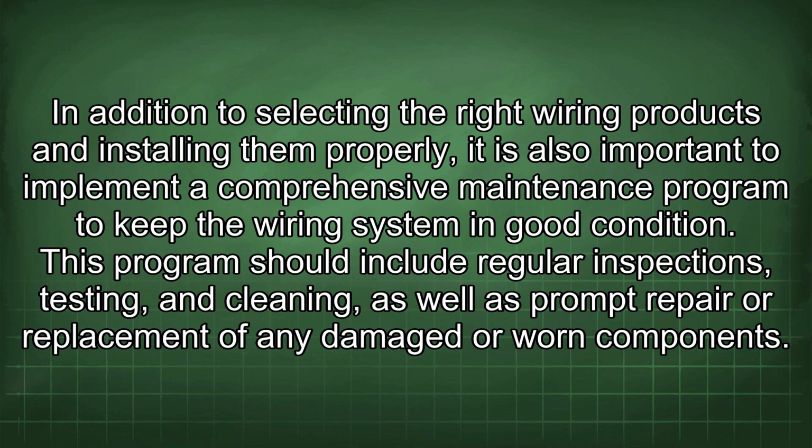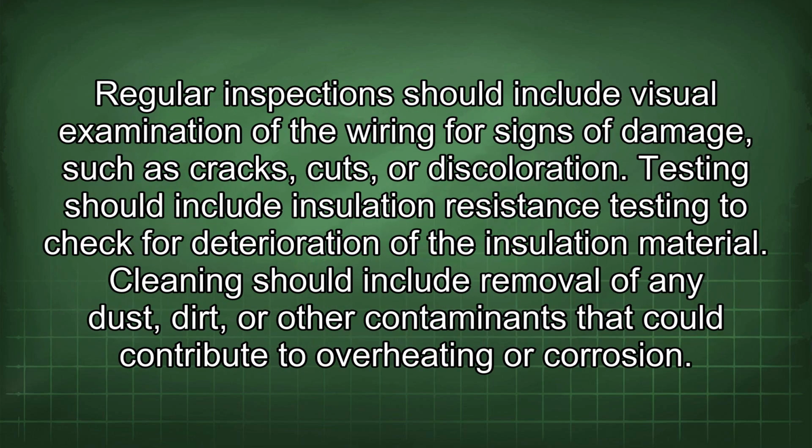This program should include regular inspections, testing, and cleaning, as well as prompt repair or replacement of any damaged or worn components. Regular inspection should include visual examination of the wiring for signs of damage, such as cracks, cuts, or discoloration.